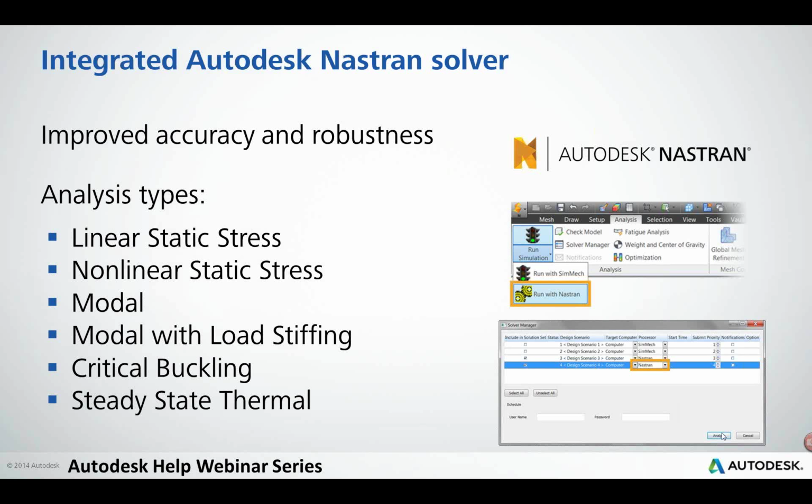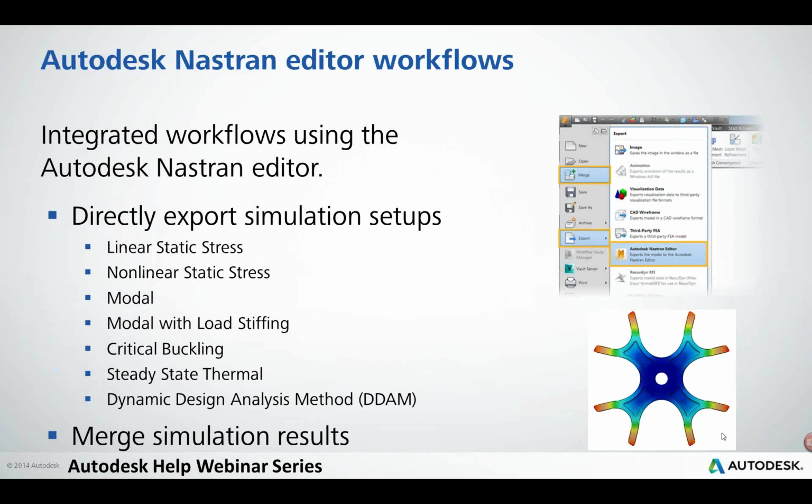And hopefully you guys have seen or used some of that information. So the other workflow, which is the workflow I'll be highlighting today, is the ability to export your setup to the Nastran editor. So this is in the application menu icon on the top left, the big S. From within the FEA editor, if you click that big S, you can go to the export dropdown and export it to one of many different formats, and one of those new formats we added in the 2015 re-release, which is also included in the 2016 release, is the Nastran editor.